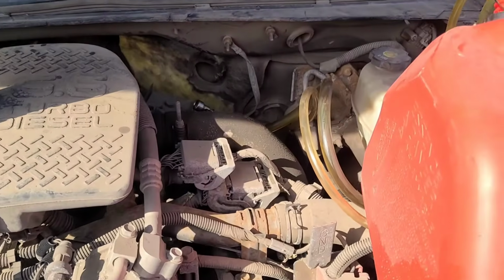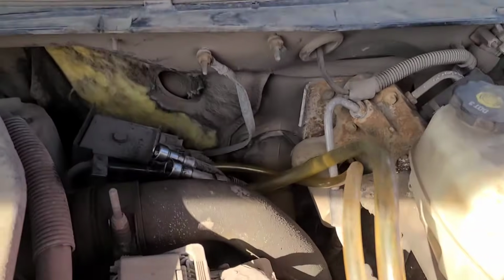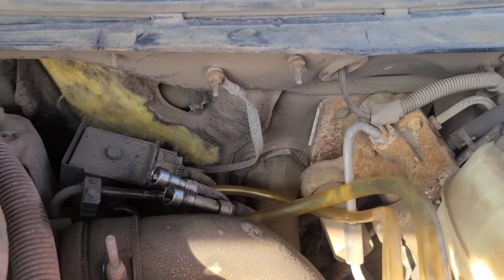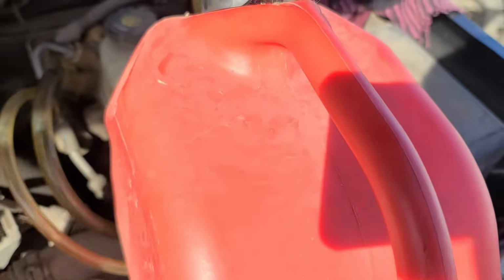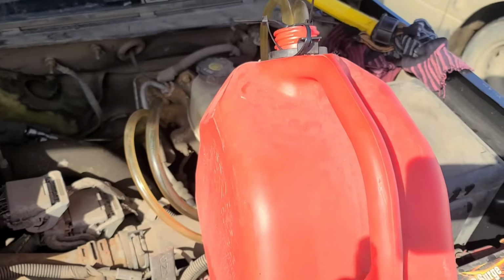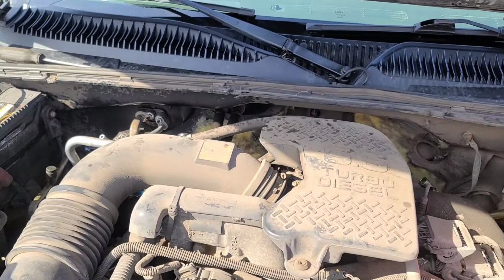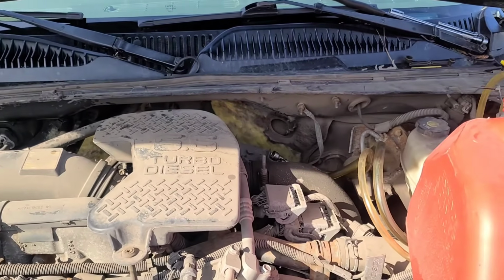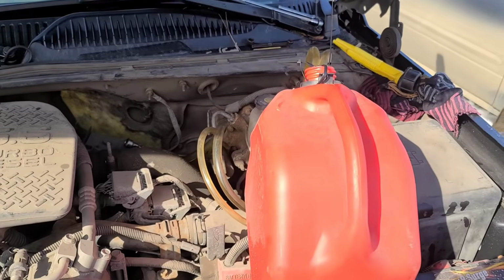So I decided rather than taking the fuel line off at the inlet of the filter, I would take it off over here at the quick couplers. I've taken both the fuel supply and return and connected them into a 2-gallon can of diesel fuel. I'm not sure what the return flow rate is like, but if I only supplied it into the inlet line, then most of the fuel would return back to the tank before I get it in the shop. I primed it now. We're going to see if it'll start.